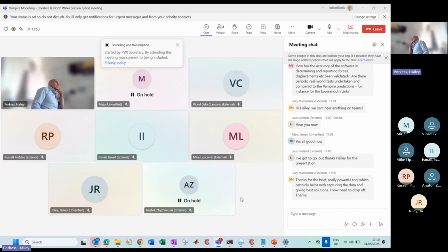So in that instance, I guess we'd look at the track geometry and we'd model all the different kinds of vehicles that are going over that site. And look to see if they get anywhere close to derailing with a plausible combination of factors, not necessarily the worst case, a plausible combination. And would that do a what-if as well then? So you could take the check rail off, put lubrication on. We can do all of that very easily. Once you've got everything set up, it's quite easy to play with numbers.